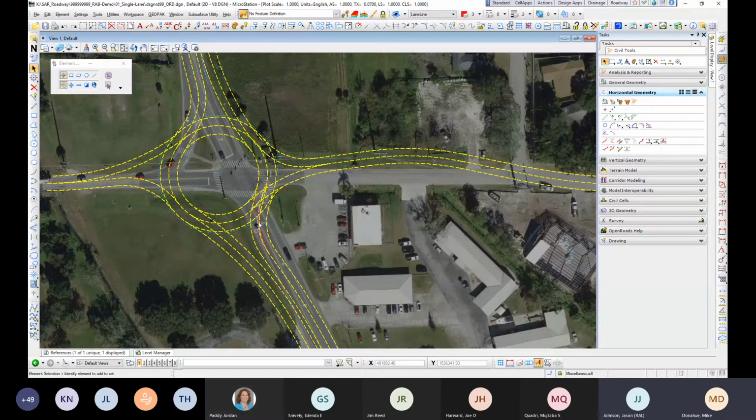So when I say detail model it, I'm creating 3D break lines for all of those lines interior, and then I'll grab those 3D break lines and triangulate them into a terrain, and then apply a surface template to give it the pavement depth for my typical section. And then I'll run a linear template on the inside for my truck apron, because that's pretty consistent. Do you do a linear template on the outside of the intersection too?